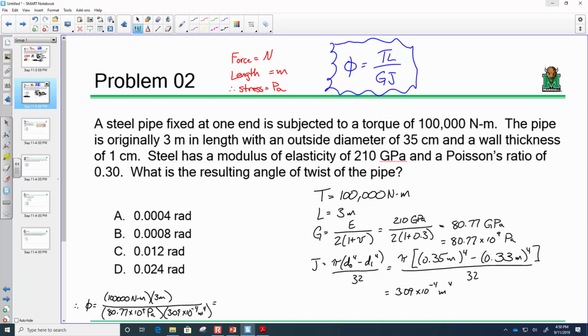Now, keep in mind, you're calculating an angle of twist. One of the things about this formula, and this is the case in a lot of mechanics-based formulas, is that when you compute angles, if you just plug and chug and don't consider units, the answers come out in radians. Because remember, mathematically, radians are a unitless means of expressing angles.